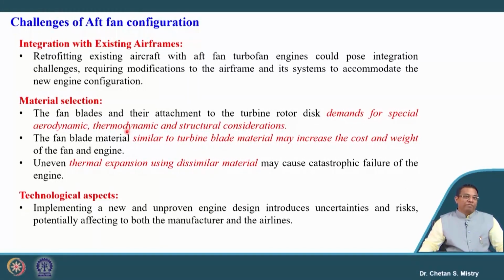At the same time, since the weight of the fan increases, it will increase the weight of the engine. Suppose we think of using dissimilar material, then in case of some metallurgical issues, that can give a catastrophic failure of the engine, and that is the reason why the airline companies are a little hesitant to move towards such kind of engine for their aircraft.